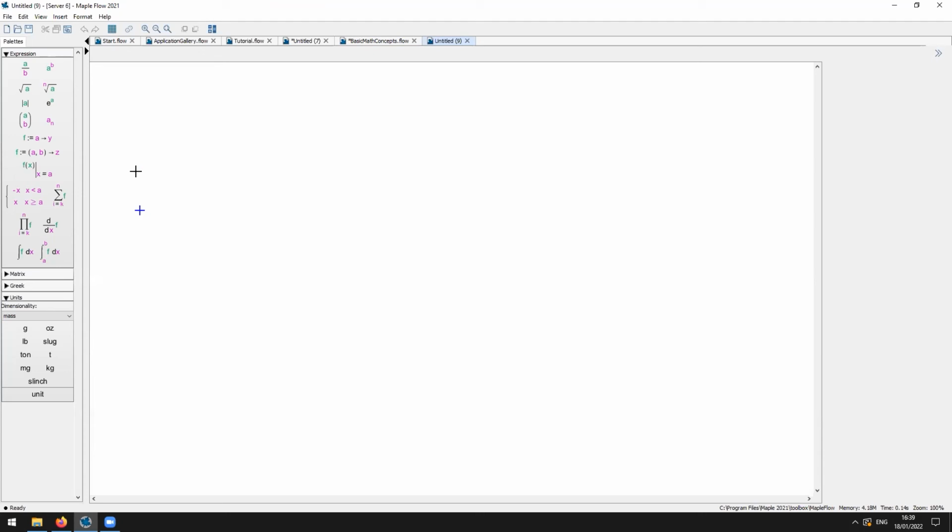And you might know that the pressure drop is defined by this equation. Delta P, I type in the delta just by entering delta with a capital D, then pressing the escape key on my keyboard.